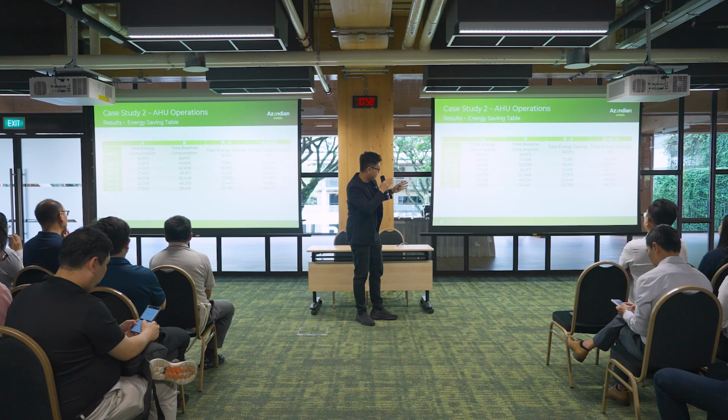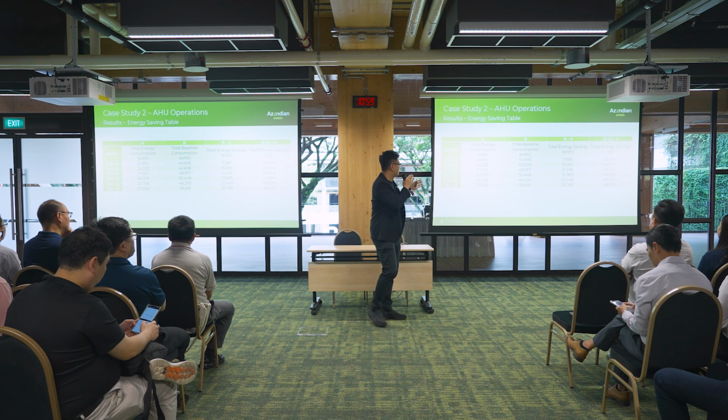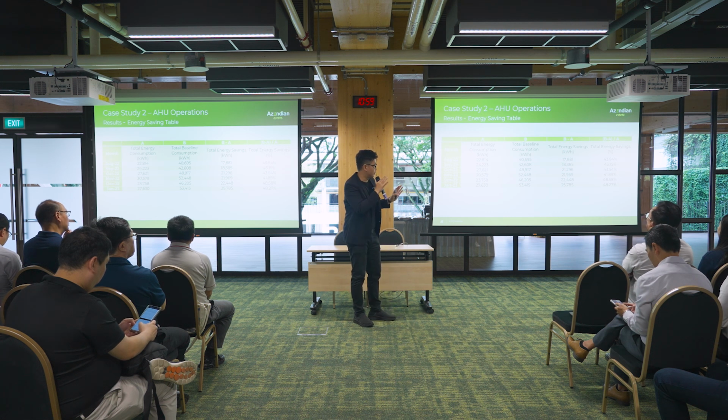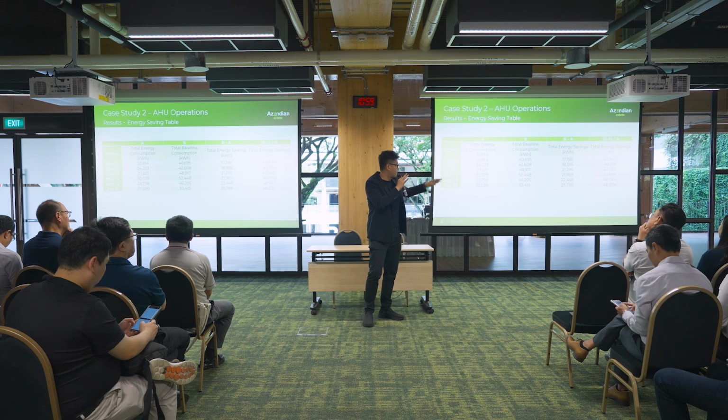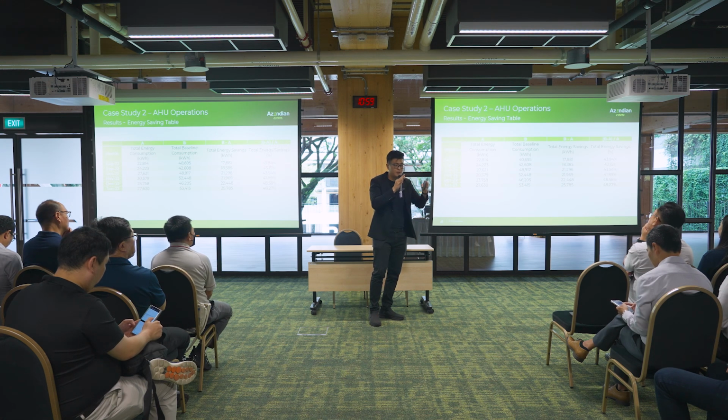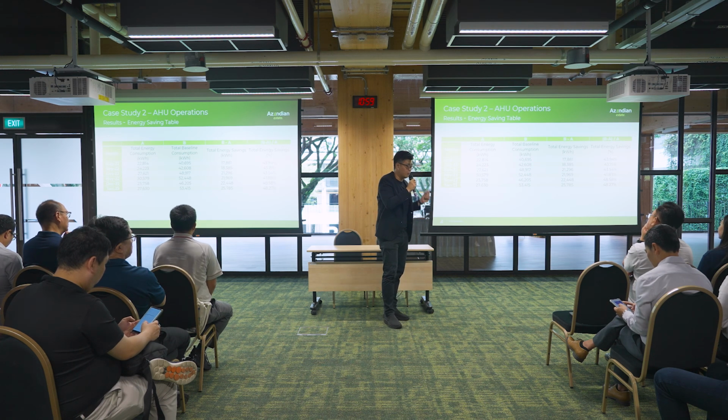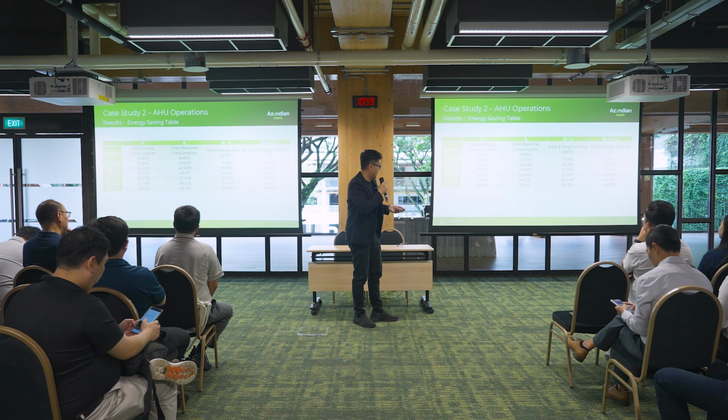I have to clarify that the savings look very, very attractive, but the project has undergone certain retrofits. Some of the issues were actually oversizing. But generally, for the fan, the fan operates based on the affinity law, right? So with this nature, every reduction in fan operating point will lead to substantial, attractive energy savings.